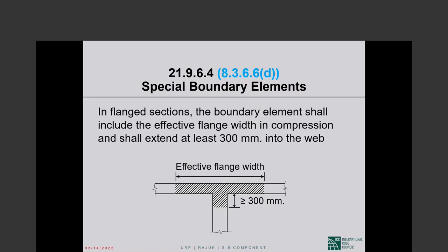Interesting question. I honestly don't know. I don't think there is any significant difference, because whether loads are attracted depends on the stiffness. Does the close stirrup spacing make the portion stiffer? At least we don't consider it in stiffness calculation. So my honest answer is I do not know. Maybe a little bit, but I don't think it is a significant difference.